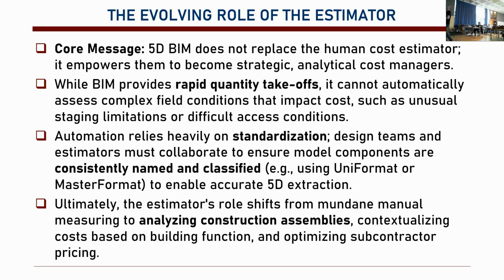In the past, estimators were continuously making takeoffs. This is what we call a rapid takeoff. So we do quantity takeoff, and we make rapid takeoffs, and we basically have to automate the process. BIM takeoff is not easy. Some people think that, well, I created the model, I will just put it in the software and it can give me the numbers immediately. It really doesn't work that way. You really need to work on it, and the estimator now needs to look into how to make that happen.